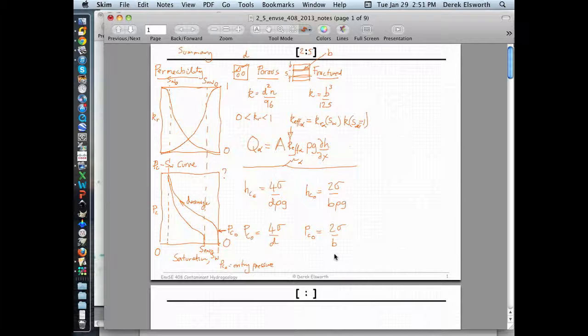The other interesting thing that we can do is that clearly these relationships are connected to each other, because they both vary with saturation. These are these no-go areas. This no-go area is here, where you can't get all the air out of the system or the NAPL out of the system. And this no-go area here is where you're left with some water in the system, even though you've invaded it completely with either air or NAPL. This would be the relative permeability to which fluid, if you look at this one?